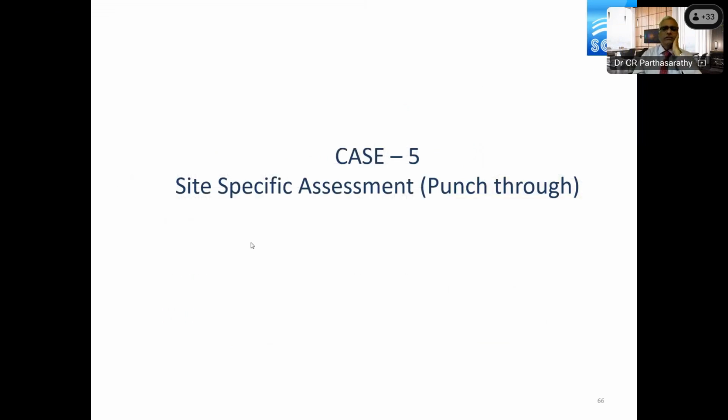So this location is site specific. We talk about the leg penetration analysis. What if the rig has to stay over the monsoon at a location? You need to make a site specific assessment. We call it SSA analysis, where for additional environmental loads, the lateral sliding, bearing, and overturning checks have to be performed.